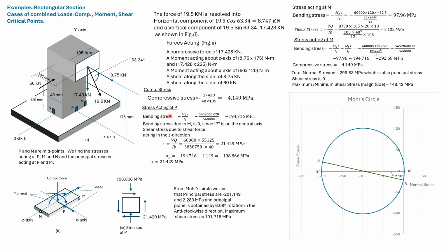Then we find the stresses at the point P. It will be subjected to compressive stresses due to both these moments. It will also be subjected to shear stress due to the 60 kilonewton load.